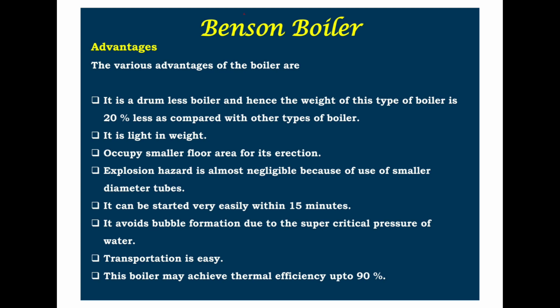Here, the Benson boiler advantages are shown. The various advantages of the boiler are: it is a drumless boiler and hence the weight of this type of boiler is 20% less as compared with other types of boiler. It is light in weight and occupies a small floor area for its erection.